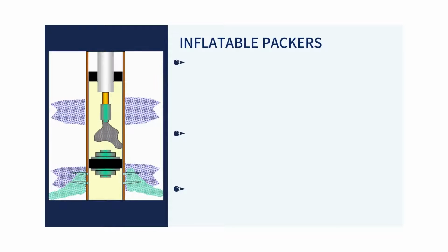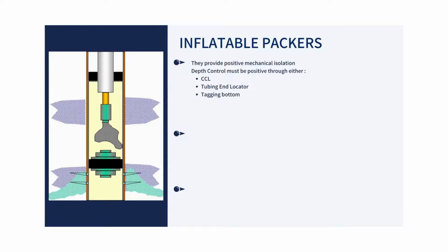Inflatable packers. They provide positive mechanical isolation. Depth control must be positive through either CCL, tubing end locator, tagging bottom, 3:1 inflate ratio, sensitive to BHT, limited amount of set/unsets.